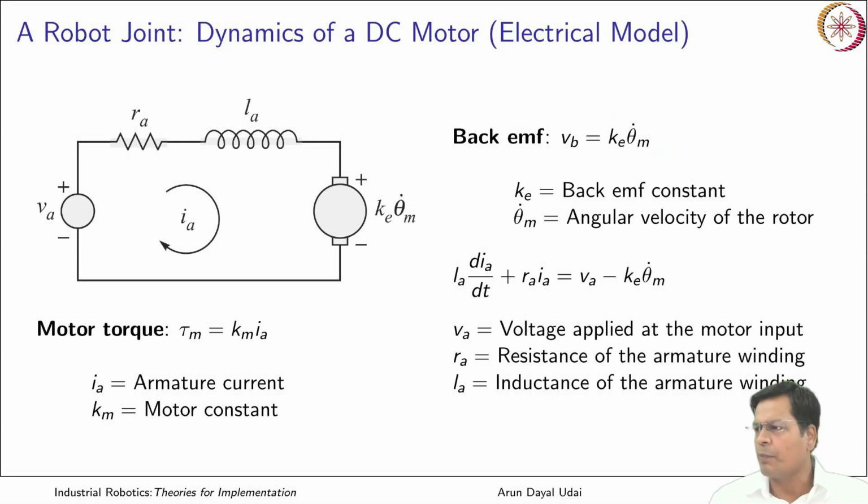Now putting them all together, what I can write is this closed circuit has got potentials across each of them. Summing them all together should count to 0. This is the applied voltage, the applied EMF, that is the driving voltage, and this is your back EMF. Subtracting them should give you the effective voltage which is present in this loop.